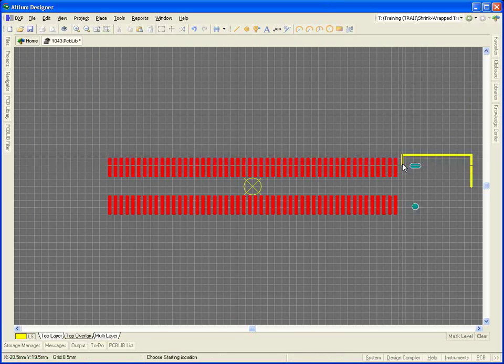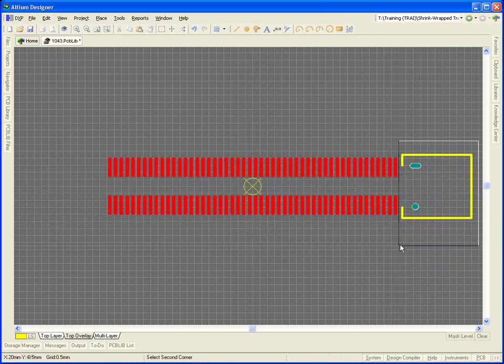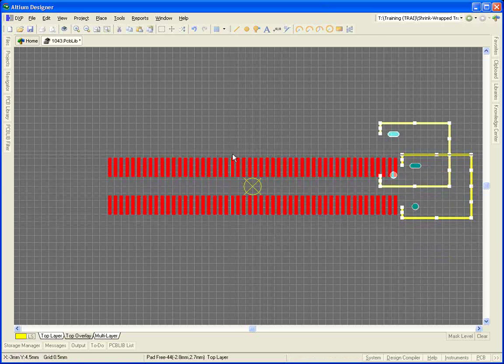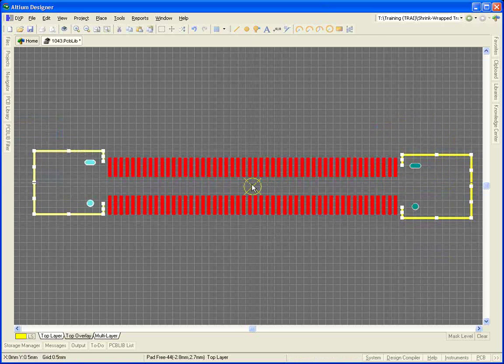Now you can duplicate that overlay detail. Select the segments, then press Ctrl C to copy them, using the origin as the reference. Press Ctrl-V to start to paste. Before placing, press Y to flip them along the Y axis, and then place them. OK, that's the right-hand end. Now you can select it all and copy, paste, X to flip along the X axis, and place.